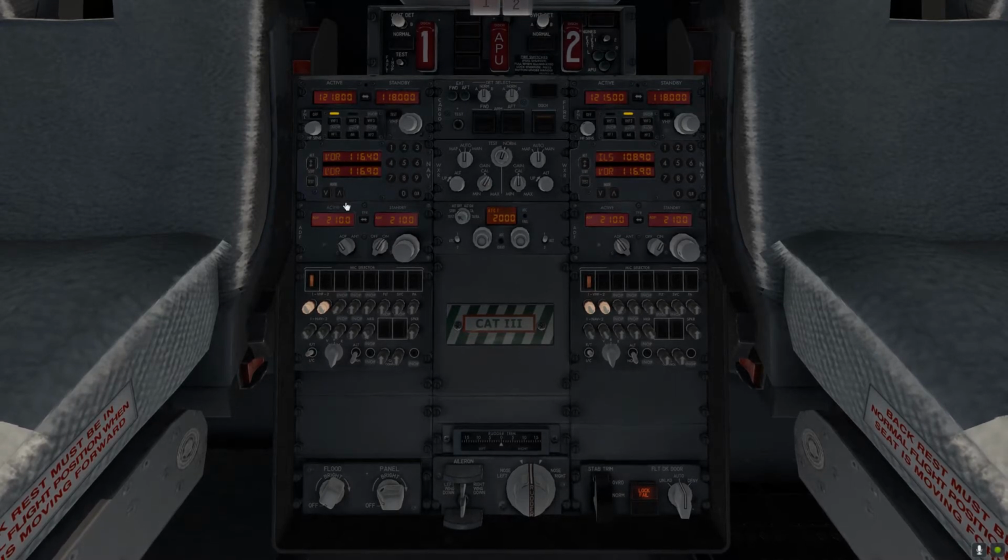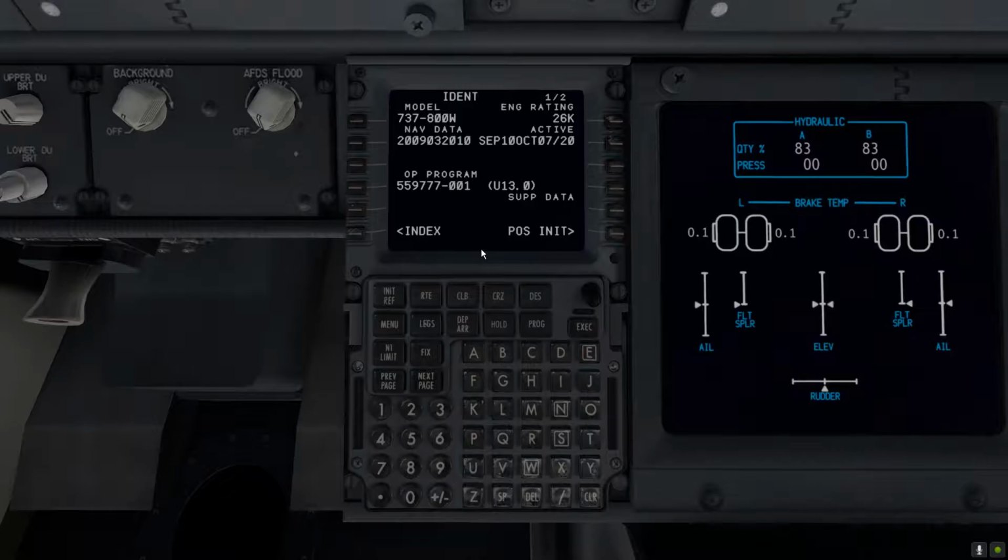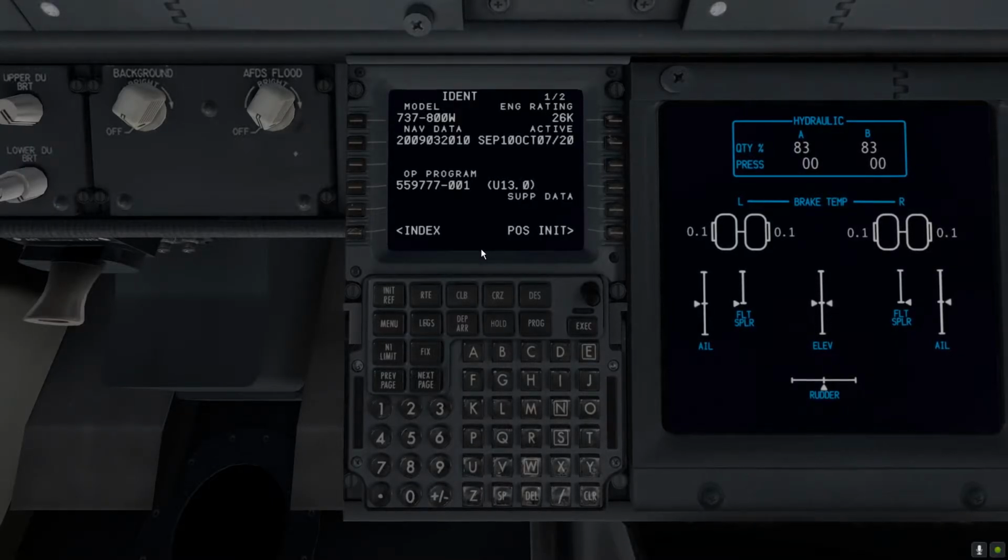108.9 as ILS. It's good also here, and in the VOR we want St. Petersburg 116.4. 116.4 is good. Now we are dealing with good frequencies. And then, yeah, let's talk about the FMC and the setting for it.